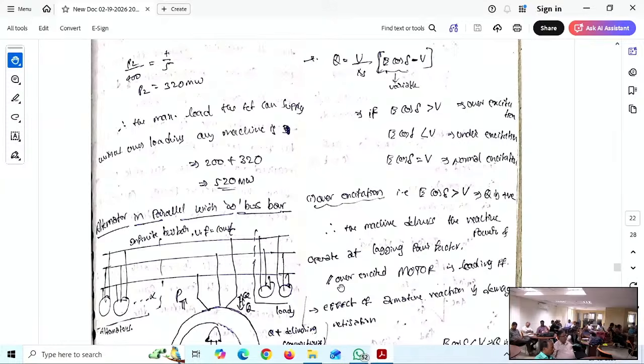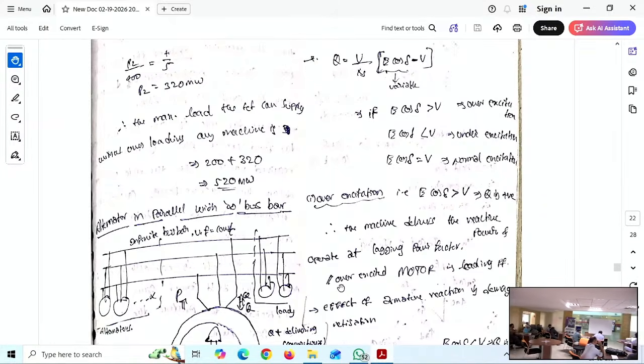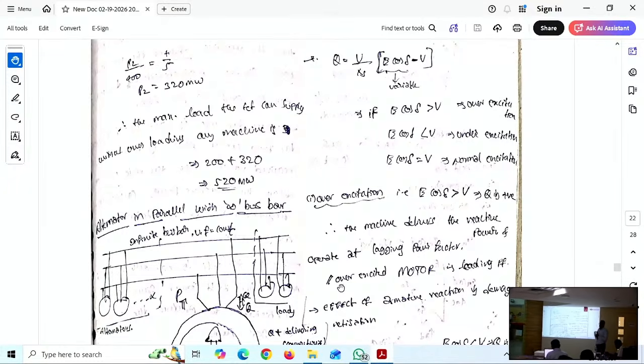After this, the case of alternators connected with infinite bus bar in parallel condition. If you keep 400 as one, machine 1 already gets overloaded. So you need not connect any load first. 400 itself is the overload. Always, whichever is lower, you keep fixed, because that is falling under the second machine's maximum value.